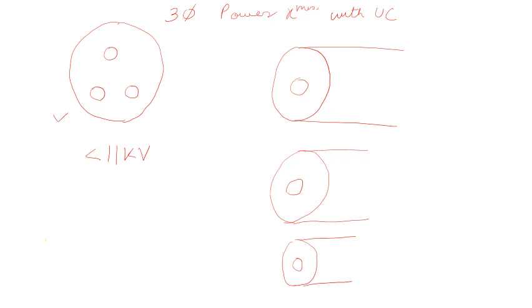And if we are transmitting above 33 kV, it is feasible to transmit through three single core cables.